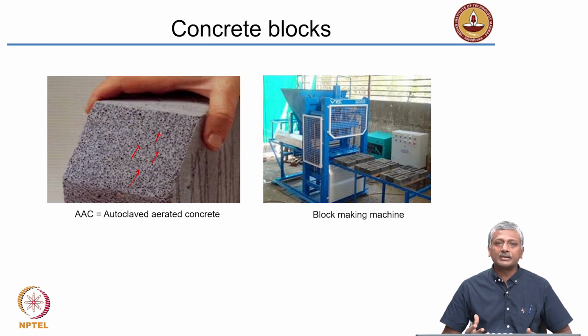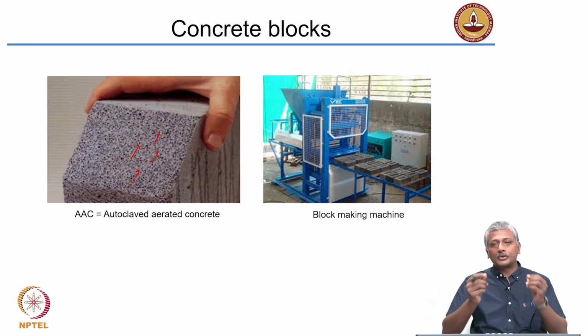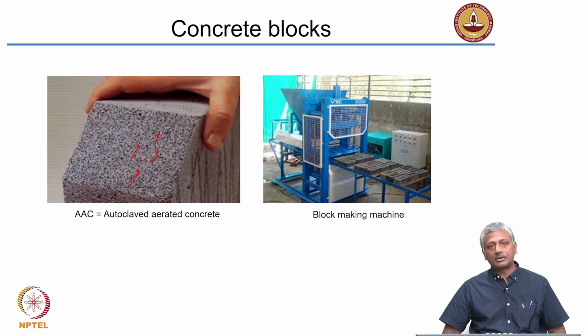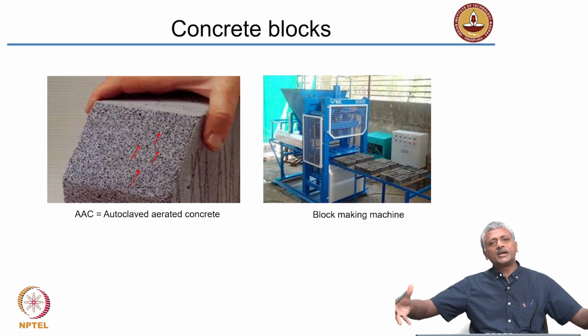You might have also seen how bakers typically bake bread, right? They put yeast. Yeast basically ferments and releases air, and that leavens the bread. Okay, that causes all these nice pores appearing inside the bread. The same process happens in the case of aerated concrete also. And because of this, what happens is the block itself, which is quite large, now becomes quite easy to handle.